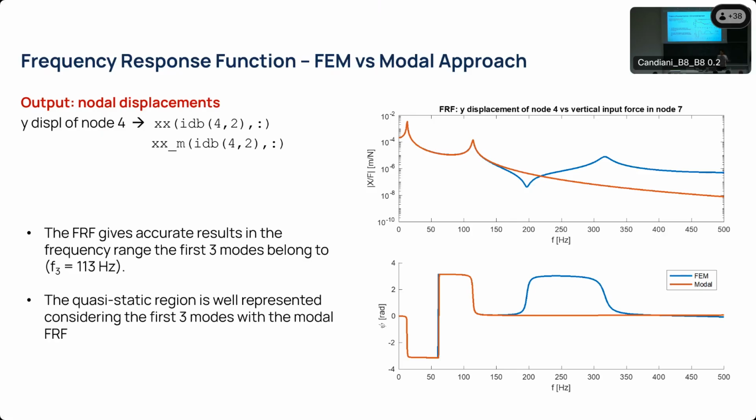From the first part of the analysis, you get the general behavior of the structure. You find all the mode shapes you are interested in, then you cut out all the mode shapes you are not interested in, because you just want to make a specific analysis, but then it's up to your sensitivity. You pass into modal coordinates, you solve the problem, you pass back to physical coordinates, and then you get your structure. So this is again the chain of thought that you have to follow to get your response.